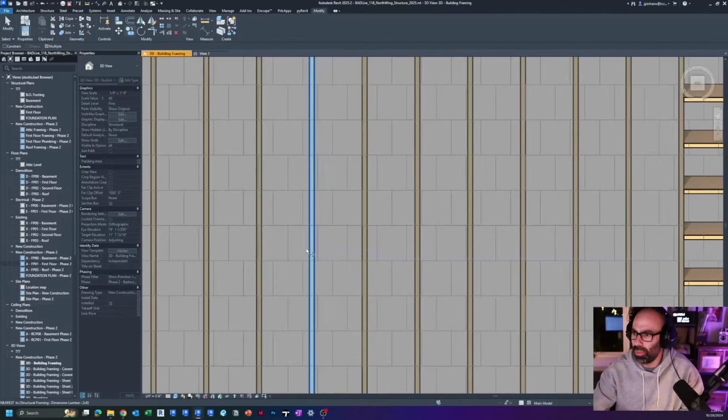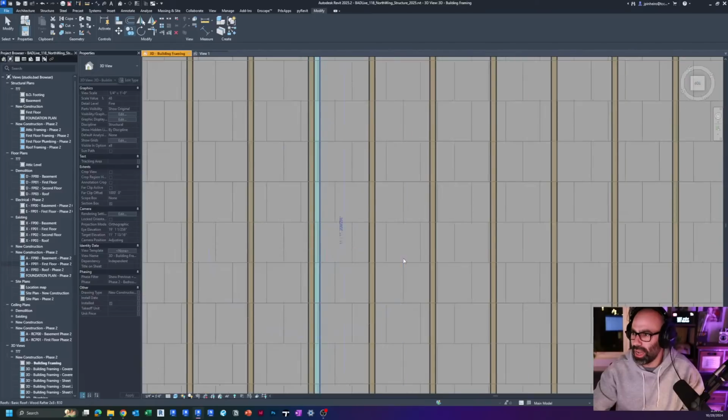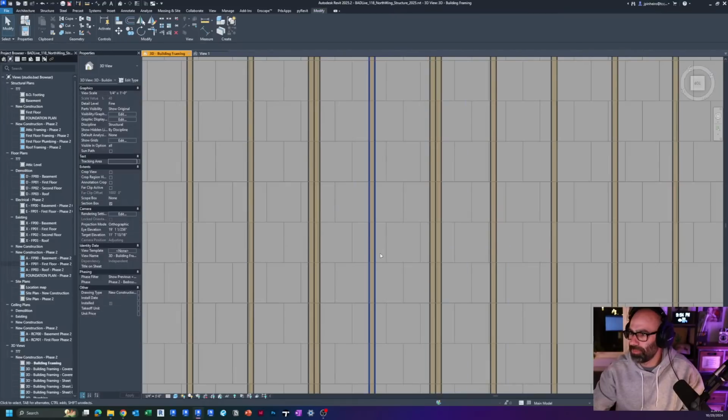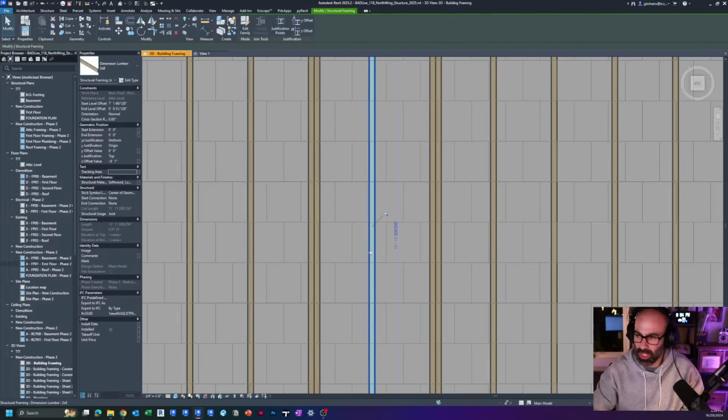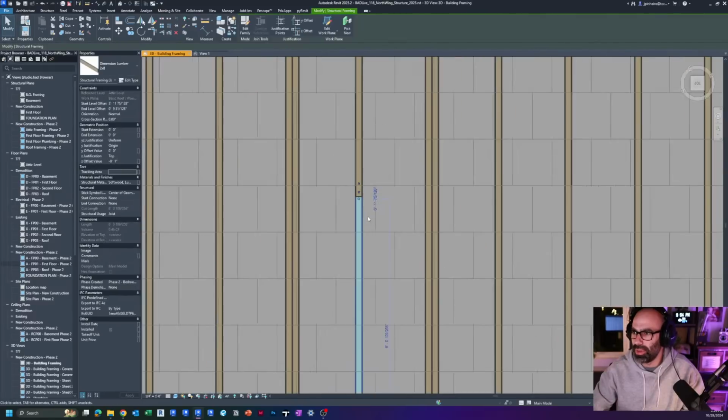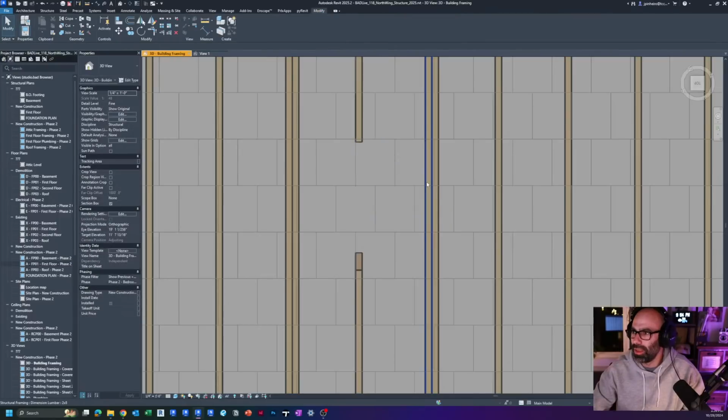if I use copy. So let's say we put an opening in here. So I'm just going to do a copy, and I'll copy it over, right? I'll unpin this so I can split it. You can't split it unless you unpin it, which means it's not part of the system, but you get it. Grab my dot, not my arrows. Okay. And now watch this.